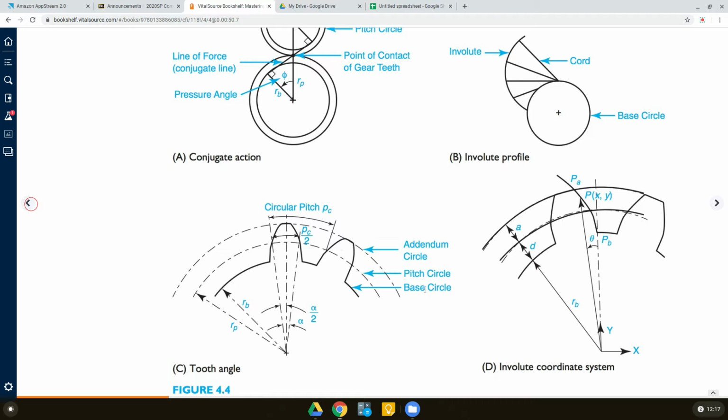And what do I mean by the right shape? That's where all the mathematics goes into getting the shape of the one tooth correctly. Once we get one side of the tooth, then maybe we can mirror it and complete the one tooth, and once we complete one tooth, then we can create a circular array to create the 20 teeth for the gear.